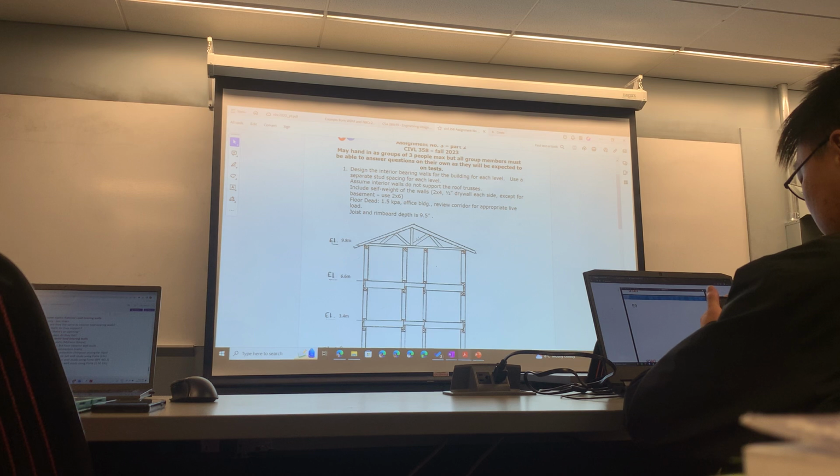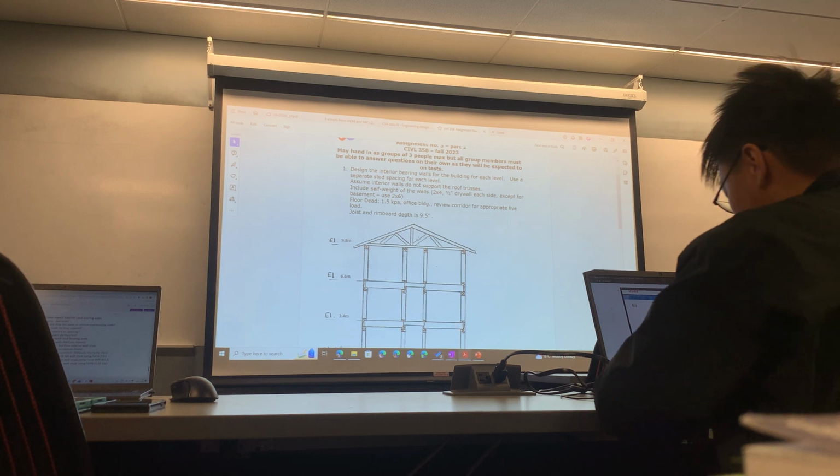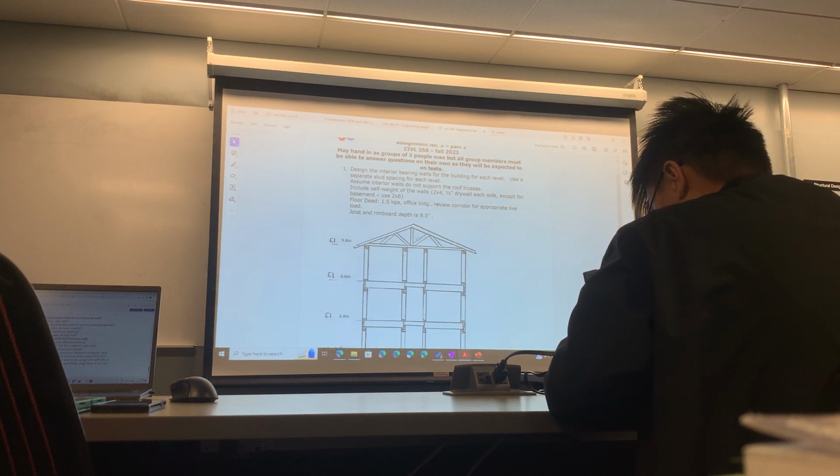When you have a wall not supporting the wall, I think what I want you to think about is what other loads are there? Self-weight of the wall. Then normally there would be the ceiling as well. Sometimes there would be a ceiling too if there's a drop ceiling, which is not clear here. And it says assume it doesn't support, so all I wanted to see was calculate self-weights. Say do it at 24 inches.